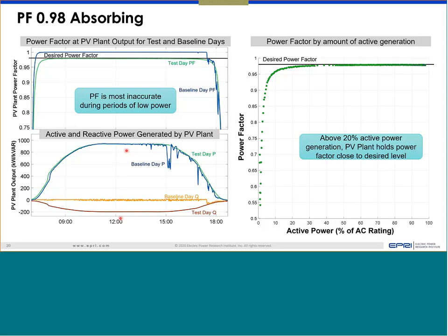And this is the amount of reactive power that the plant will be absorbing on that day. As a distribution operator or transmission operator, your question will be, if I have hundreds or thousands of them in a substation all absorbing, where will the reactive power come from? So that's why it's important: yes, a more aggressive power factor may help with the voltage more, but on the opposite side, from the customer side there is an impact on energy production, and from the utility side, you have to provide that reactive power from somewhere.